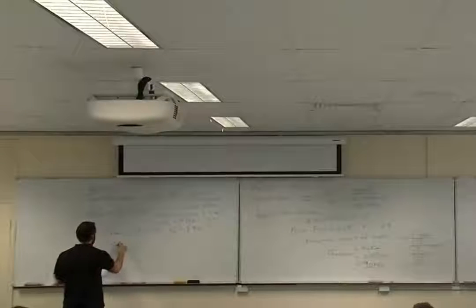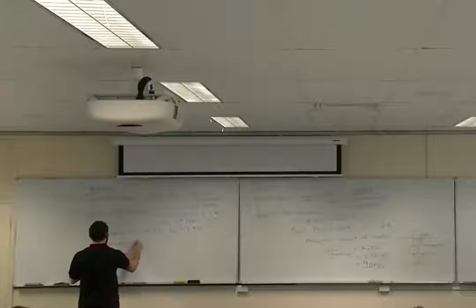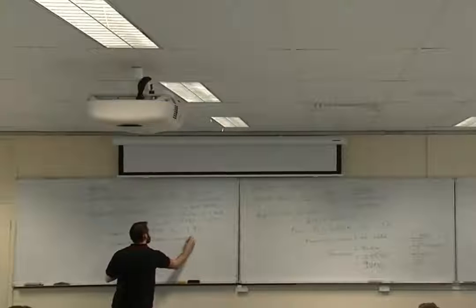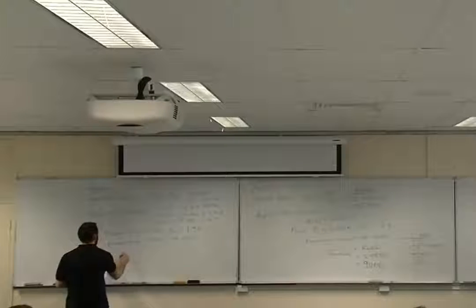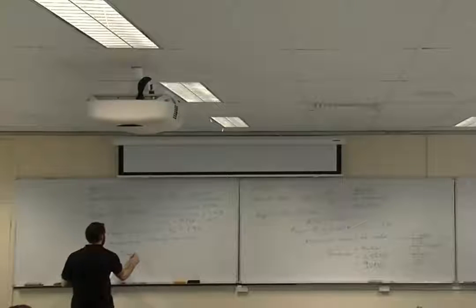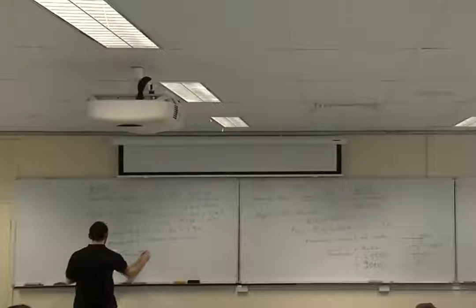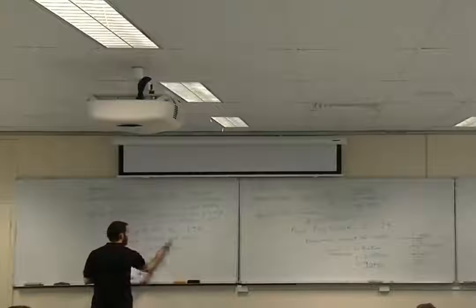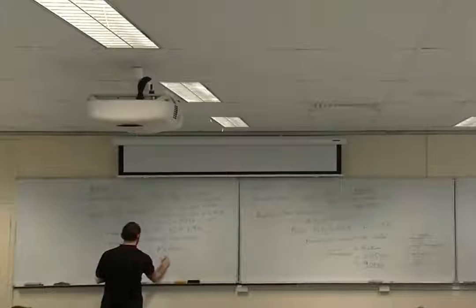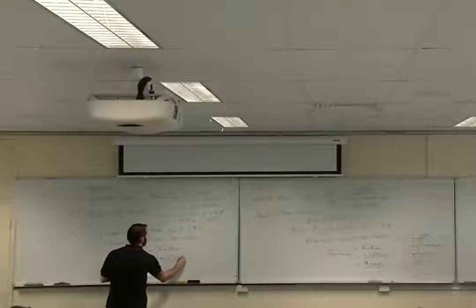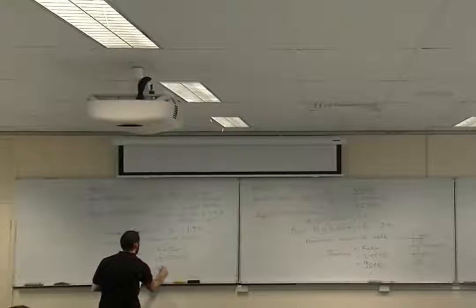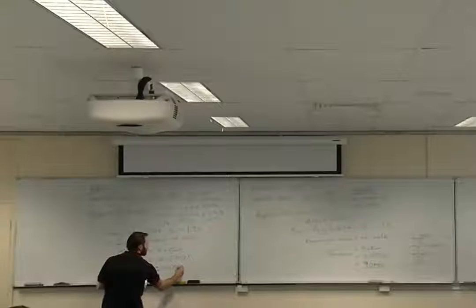Therefore, maximum stress at notch, sigma max (notch), equals KT sigma nom, equals 1.95 times 25.7 equals 50.1 MPa.